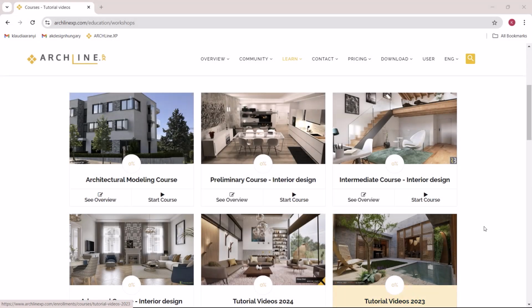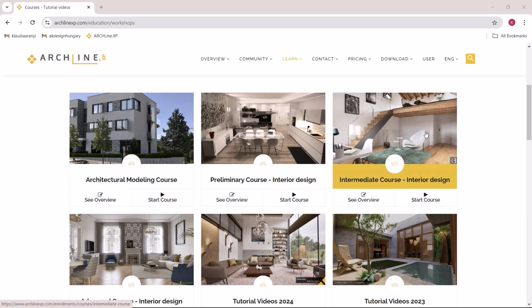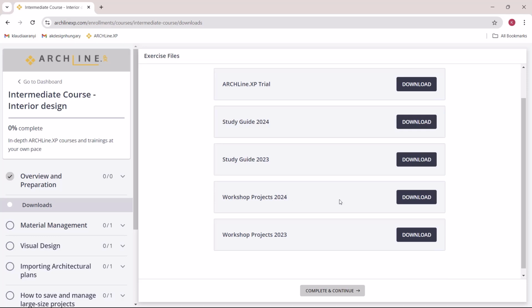I welcome you to today's training video where I will present the design phases. With the help of the phase and phase filters, I will create a new plan starting from the state of an existing plan. The phases can be tracked in full documentation, so 3D views, sections, elevations, and quantity lists follow the status of the current phase.